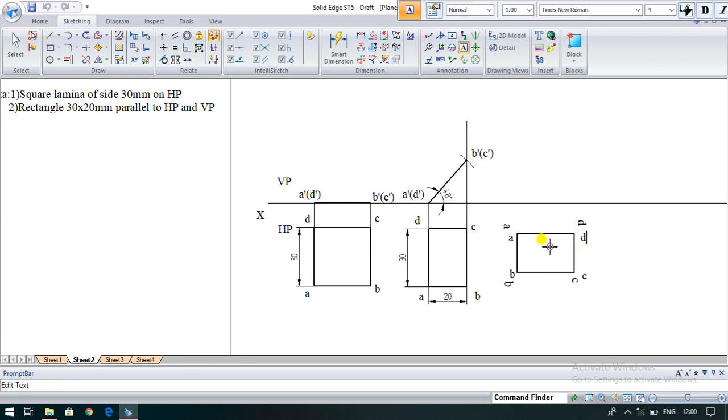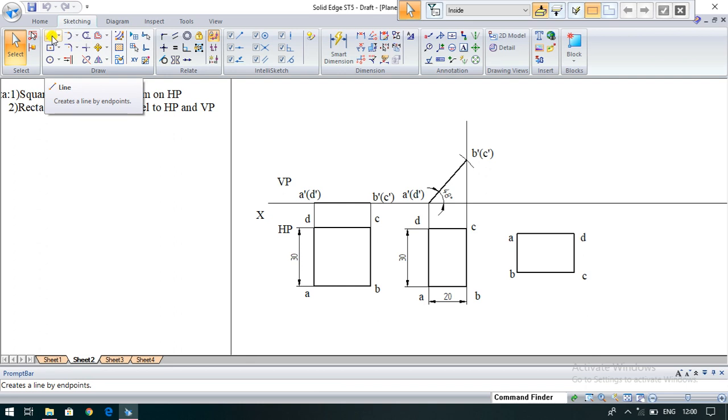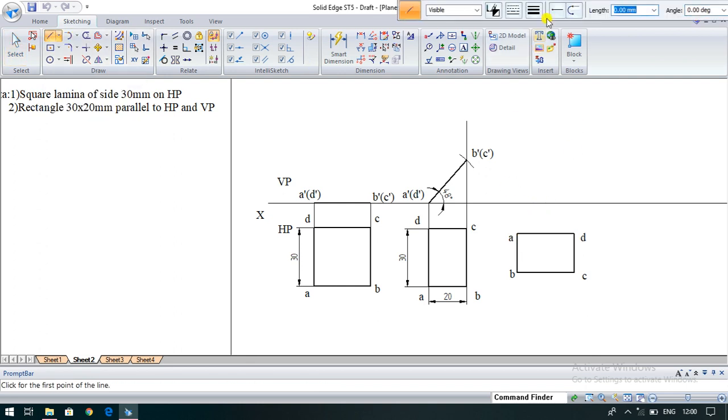For easy visibility, we can delete this one. Delete all the rotated commands. Select and delete it. Okay. So after rotating the same rectangle at an angle of 90 degrees, now project the lines from each point from top view to front view. So up to extend I want up to here. So we have to draw up to the dotted line where exactly it shows. Okay.